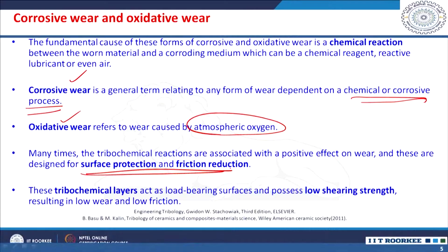These tribochemical layers act as load bearing surfaces and possess low shearing strength, resulting in low friction and low wear. So, if the layer has less shearing strength, it will be easy to slide. So, you will not have a friction increase, right, and the material removal can be subsequently reduced.